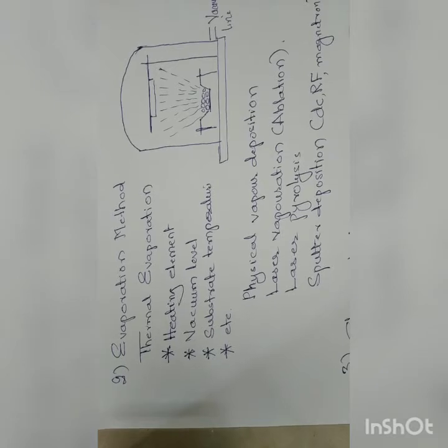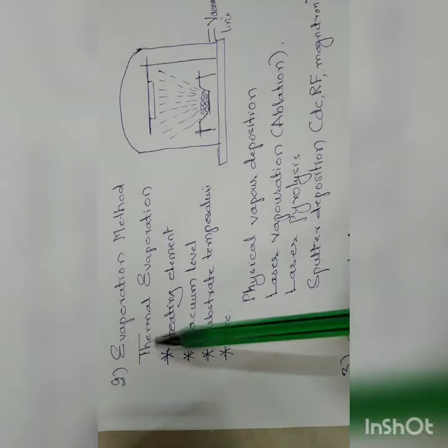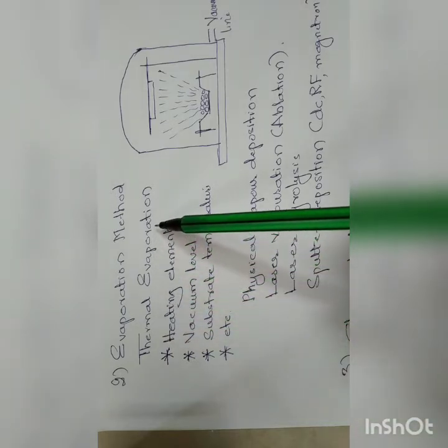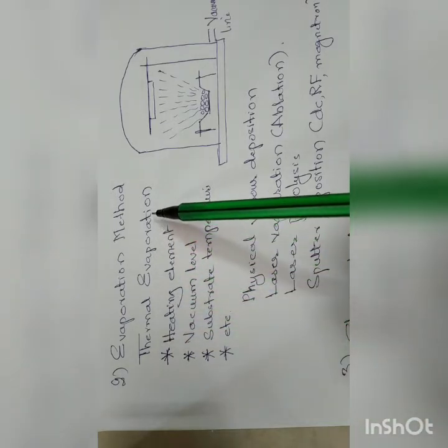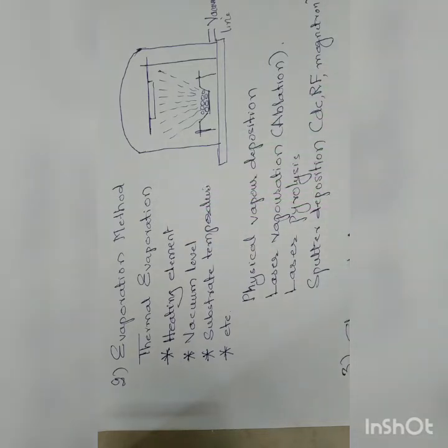Now let us come to another technique of making nanomaterials. As I said earlier, that is the evaporation method. There can be many evaporation methods, but what I have quoted here is thermal evaporation. This is a very simple and commonly used technique, because you can simply design and assemble it. So the basic concept goes like this.